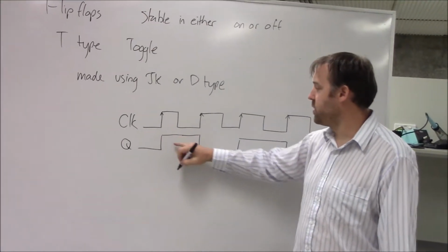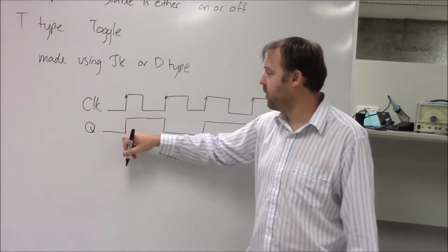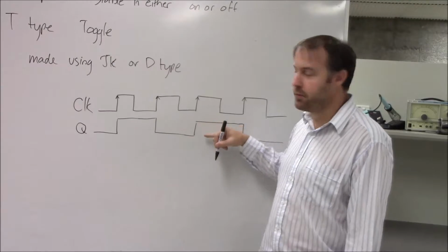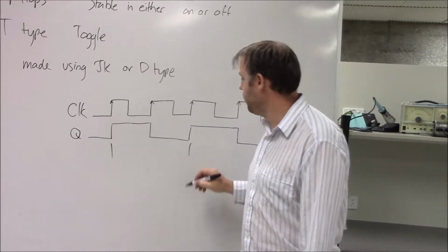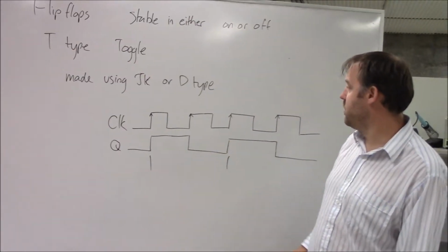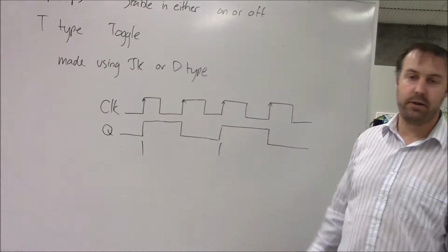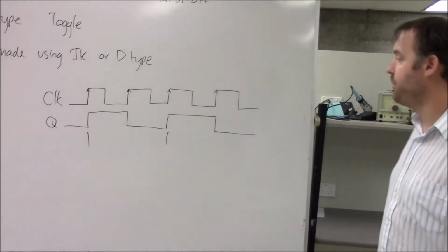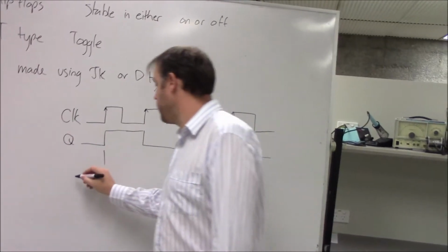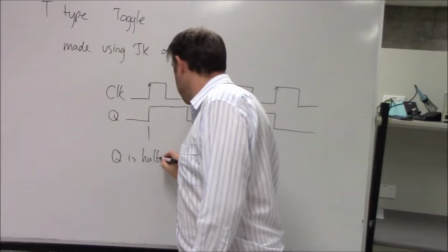until each rising edge. So it changes once a second, but it doesn't do a full cycle, going from low to high, back to low again, and then this is one full cycle of our output here. That changes at half the rate that our clock signal does. Okay, so half the frequency. So Q is half.